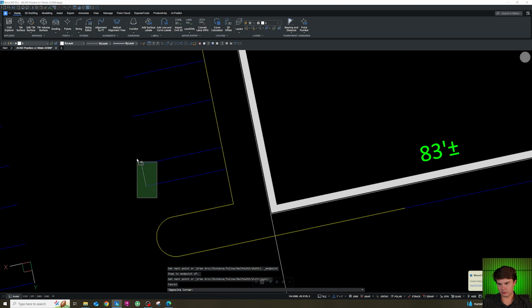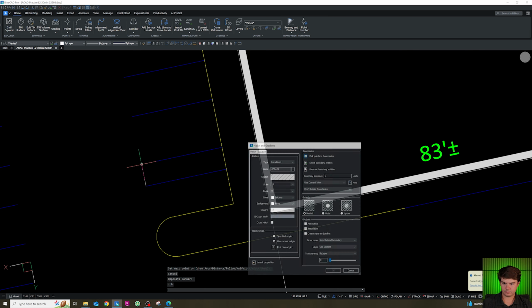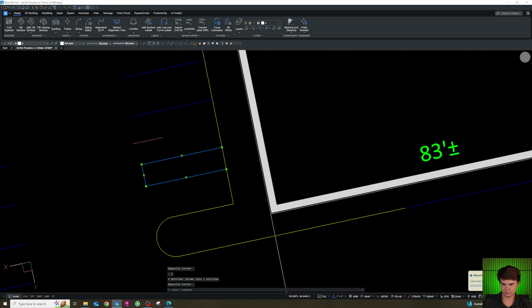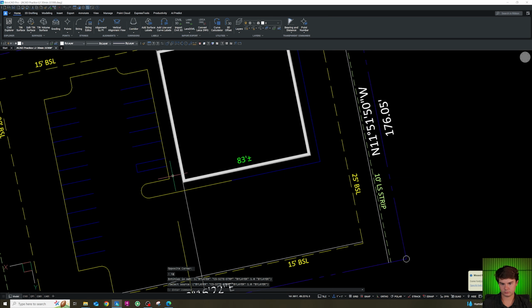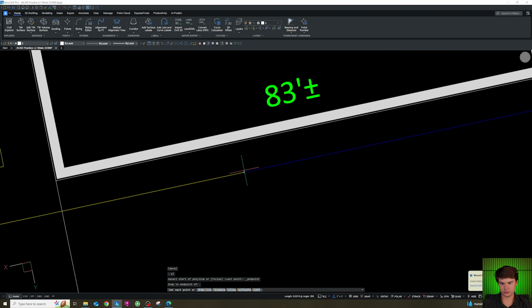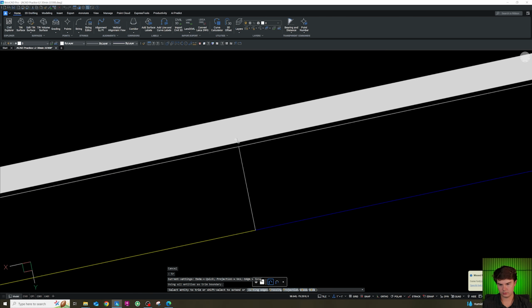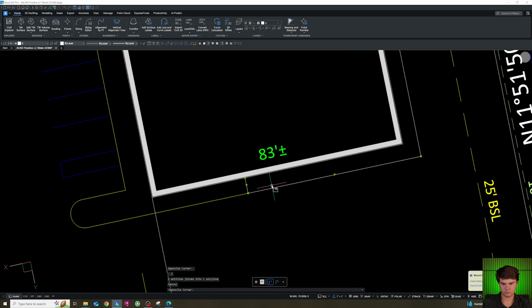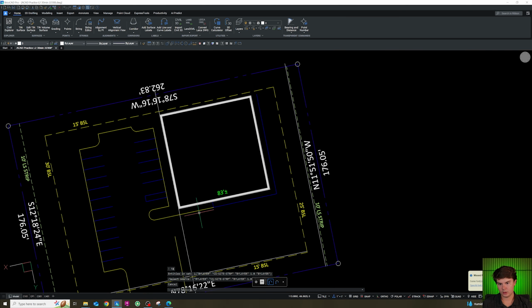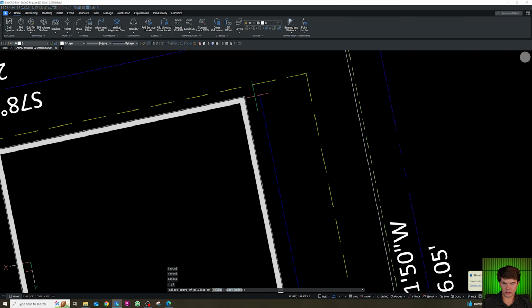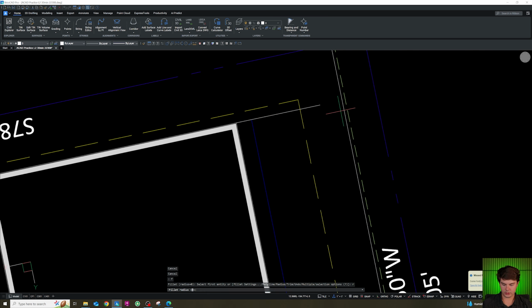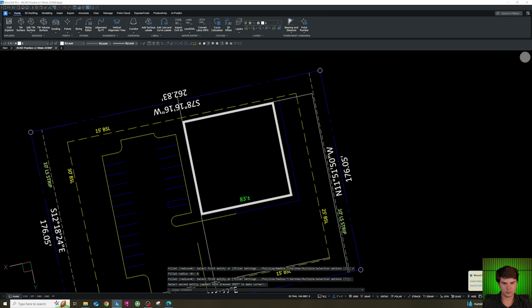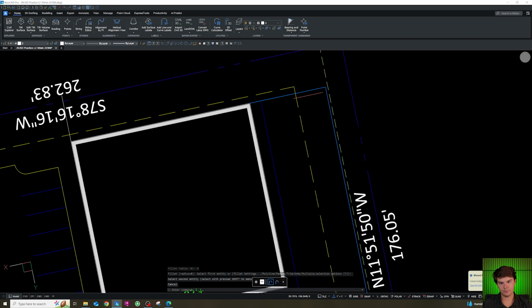I'm going to close off our area for a hatch later. Also going to close this off for a hatch later. Perfect. Now it looks like our drive aisle ends with the building up here, so I'm going to draw a line ortho to that and connect this with the 0 radius. So this will come down. Go ahead and put this on the concrete layer.